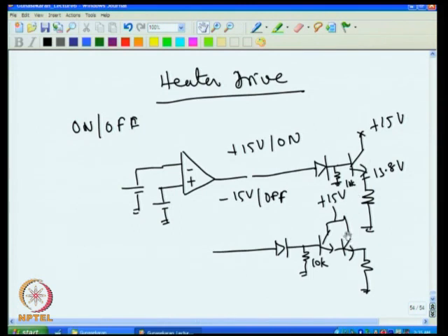In this case, for high current, we can have a Darlington. For example, this can be 3055 and this can be 3019. So, 10 milliampere here can become 1 ampere here per HFE of 100, and for a high power transistor the HFE is low, that is 20, then up to 20 ampere current can go through this, provided we put a heat sink for this transistor. We have discussed the heat sink design in our earlier lecture. The same thing can be used here.